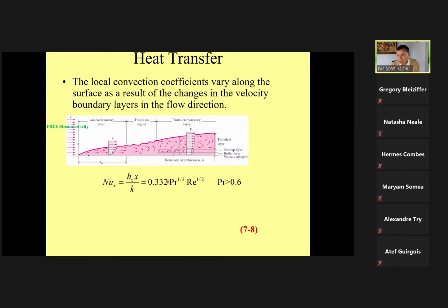And here's the constant we discussed last lecture. This is the Prandtl number. We measure it only as a characteristic of the fluid we're dealing with, whether it's a gas or a liquid, air, or whatever it is, and it has nothing to do with the rest. And here is the Reynolds number. In general terms, we always define the Reynolds number as density, velocity, and a characteristic length divided by viscosity. The characteristic length changes from geometry to geometry. Look here, before we said we have a flat plate, a vertical ball, and a cylinder. Therefore, we have to be careful when defining the Reynolds number. It depends on the shape we are dealing with.